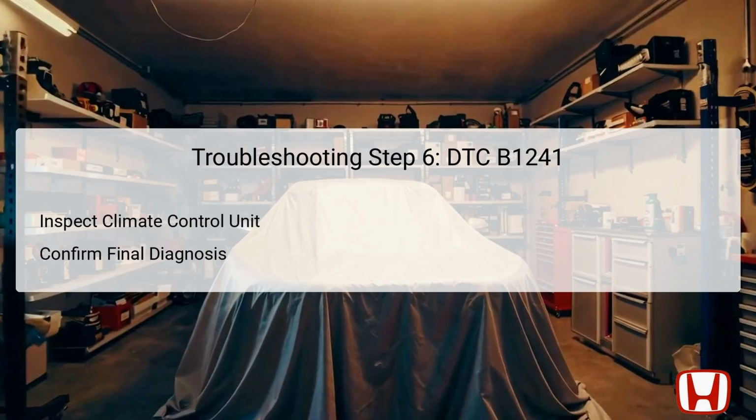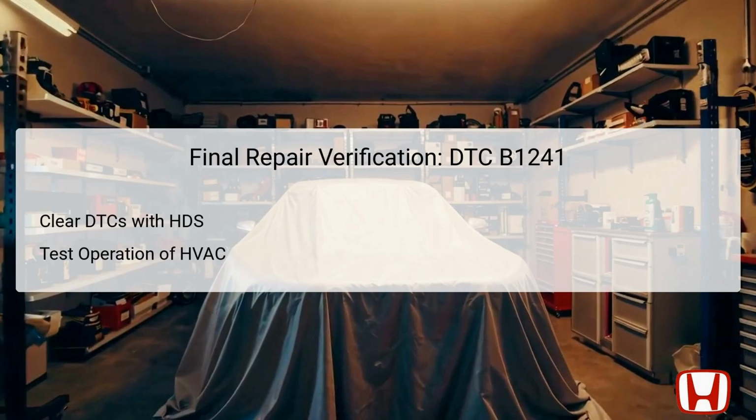The climate control unit is responsible for interpreting the feedback from the blower motor and controlling operation. If determined to be defective, it will likely require replacement to restore overall climate control functionality. Once repairs or component replacements have been conducted, it is essential to verify that the issue has been resolved entirely. Start by clearing the diagnostic trouble codes, DTCs, using the Honda Diagnostic System, HDS.